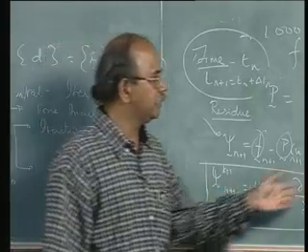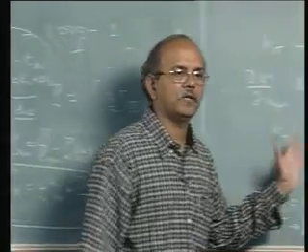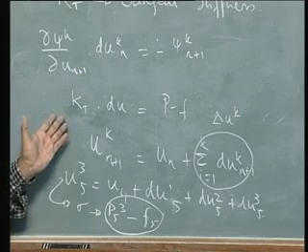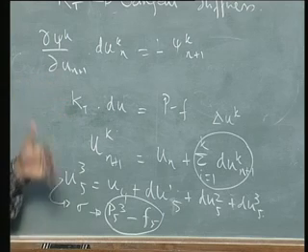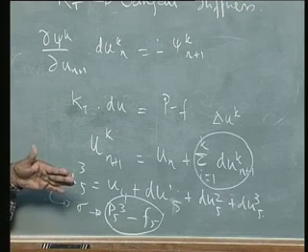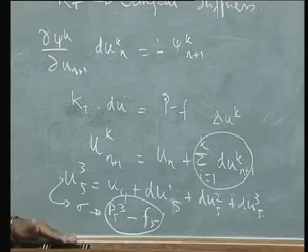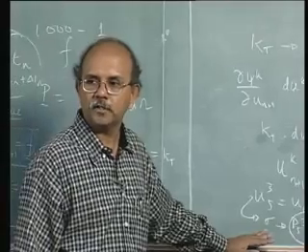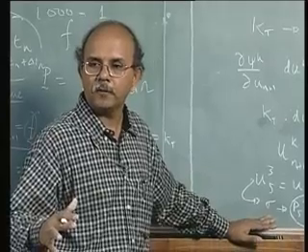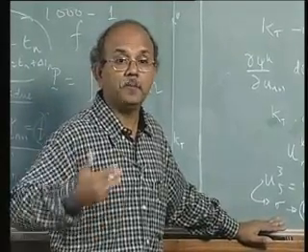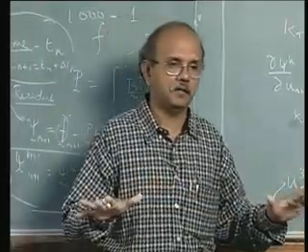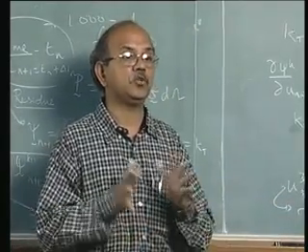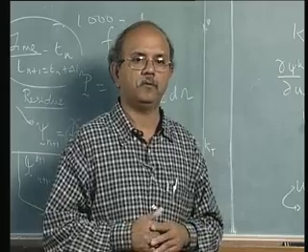From this, we came back to our very familiar simple simultaneous equations, defined tangent stiffness, and solved it. For every iteration, we keep a watch on this residue. If the residue happens to be very small, we are happy with it, go to the next step, and so on. We keep repeating these steps until we finish the problem, or when t becomes t total, say 1 second, as we had defined before.